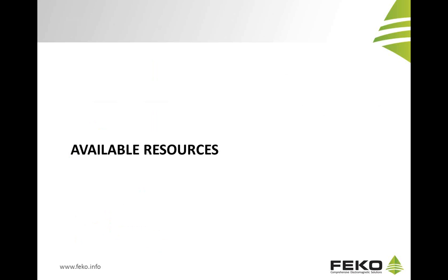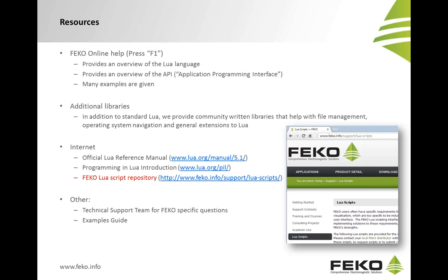Now, the script that I just showed you might have seemed a little bit daunting. The Lua language itself is actually quite simple, but the API to the FEKO suite is complex due to the complexity of the applications themselves. So we recommend that you start by, first of all, going through the Lua language basics. These are available online. You will see on the internet there are links to the various tutorial and reference manual sites. And then we also have a full API documentation in our online help and PDF manuals.